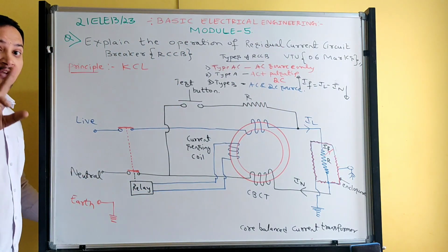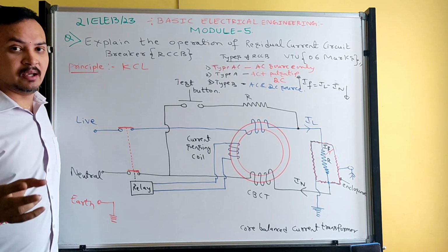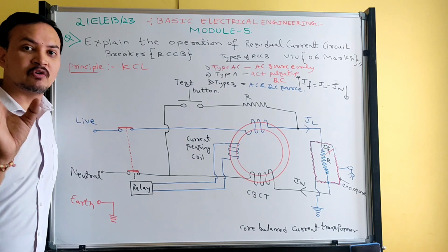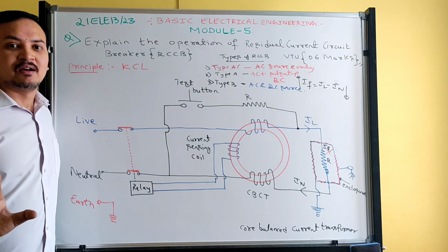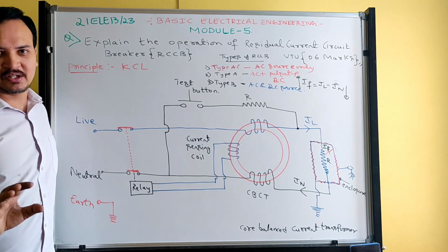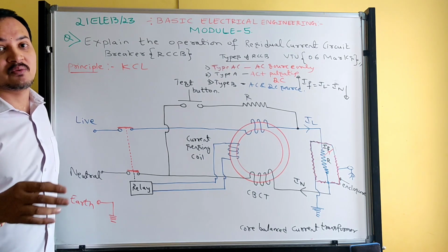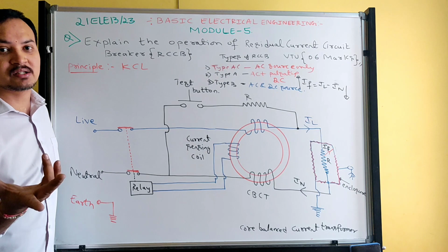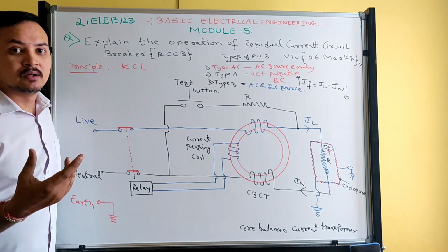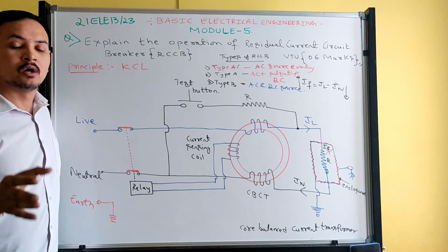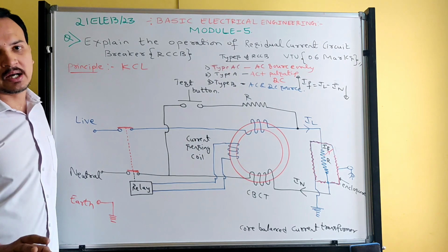See, keep in mind the difference between MCB and RCCB. MCB is used for short circuit protection. MCB will not give earth fault protection. RCCB will give earth fault protection, but RCCB will not give short circuit protection. But in the worst case, if both faults occur in real time, we need to protect against both faults. Therefore we need to use both MCB as well as RCCB.